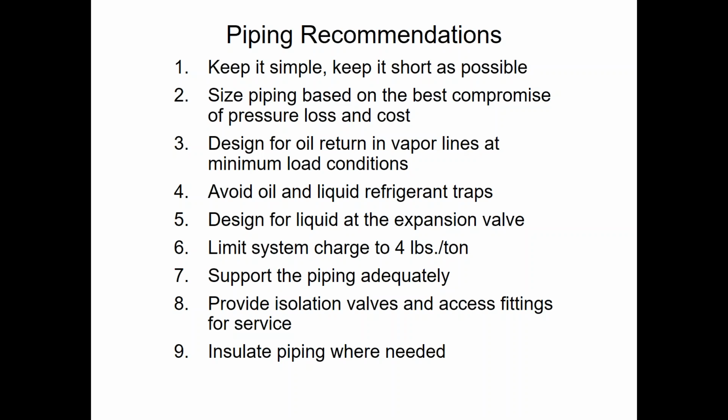In sizing pipe, regardless of whether it's a liquid, a suction, or hot gas line, one of the things we need to look at first and foremost when we're looking at the routing is the shortest distance between A and B, between the compressor, the condenser, and the evaporator, or from the chiller to the barrel. What's the shortest possible distance? In other words, let's keep it simple. Keep it short, keep it simple. That's rule number 1 with piping.